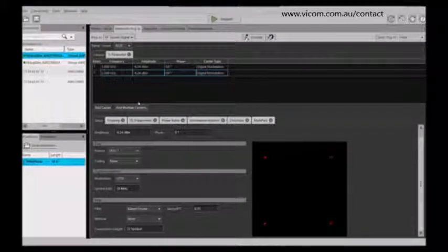So this is a nice thing about using an AWG for a signal generator for RF applications, is that you can have multiple carriers on one waveform rather than having multiple generators creating your single carriers. So this is a very useful tool, and this is why AWGs are so popular in the RF industry today, to be able to build these very complex waveforms.